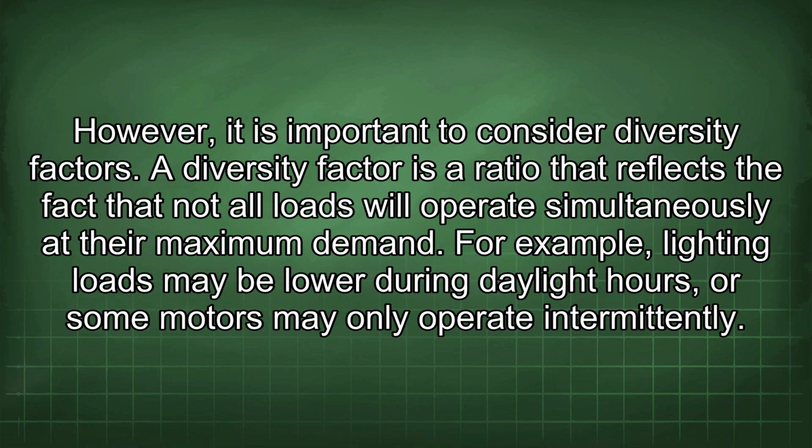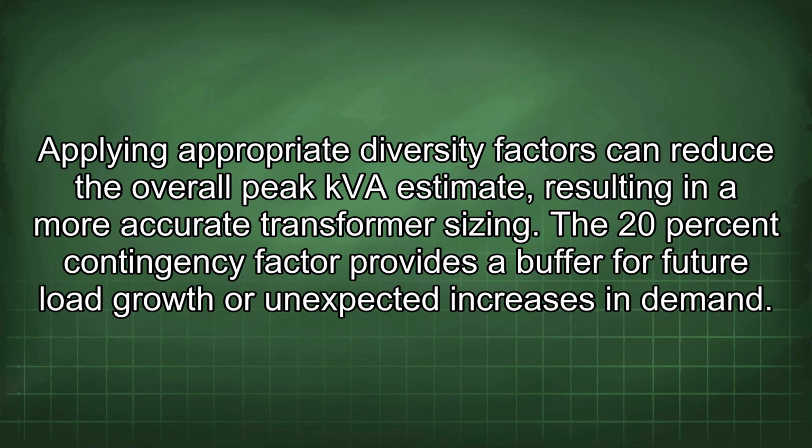However, it is important to consider diversity factors. A diversity factor is a ratio that reflects the fact that not all loads will operate simultaneously at their maximum demand. For example, lighting loads may be low during daylight hours, or some motors may only operate intermittently. Applying appropriate diversity factors can reduce the overall peak KVA estimate, resulting in a more accurate transformer sizing.